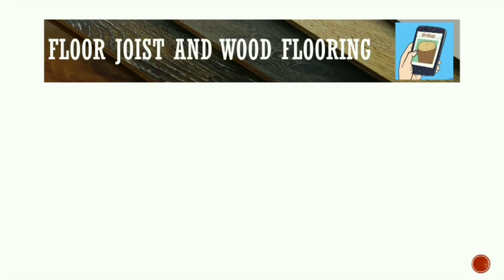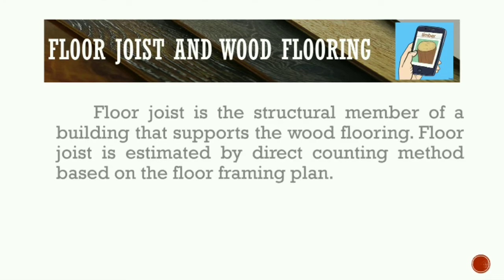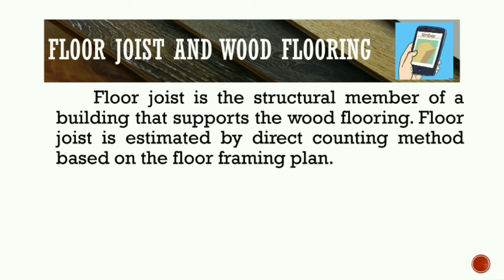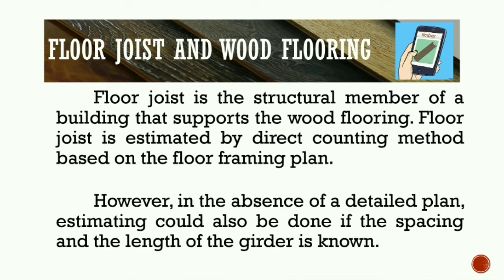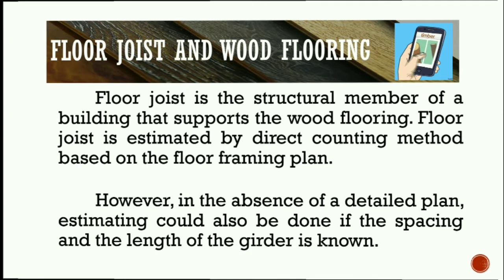Now for the floor joist and the wood flooring. The floor joist is a structural member of the building that supports the wood flooring. So the floor joist is estimated by the direct counting method based on the floor framing plan. However, in the absence of a detailed plan, estimating could also be done if the spacing and the length of the girder is known.